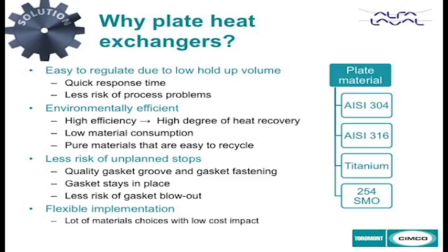And we have as well so many different plate materials that we can use. For example, for brine, we can use SMO or titanium, while in glycol, we normally use stainless steel 304 or 316.